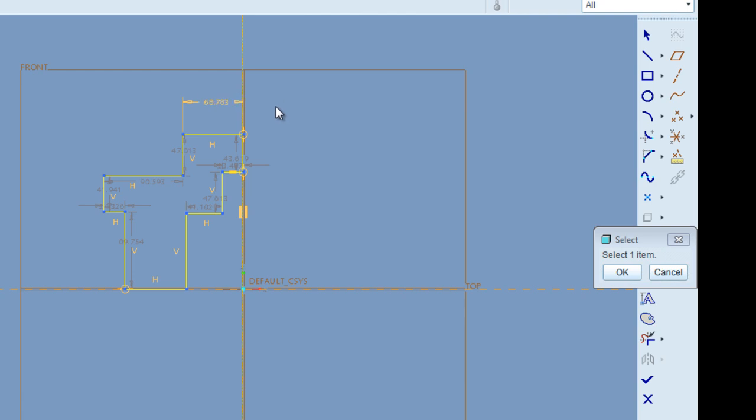We have an arbitrary number here, which represents our radial dimension, meaning that if we revolved this feature around the center axis, this would define the radius of the part. Normally, if you're measuring with a pair of calipers, you're measuring the diameter. It would be a lot of work for every diameter that you measure to divide by 2, especially if it's an odd number.